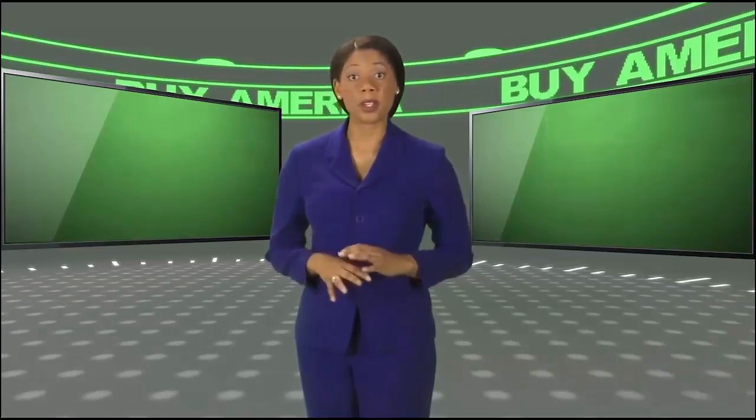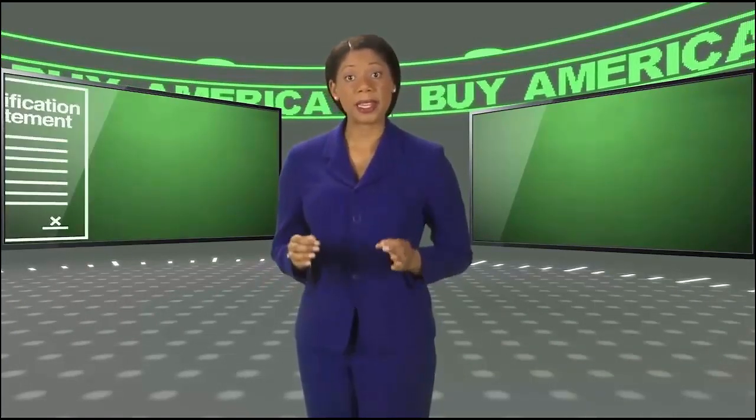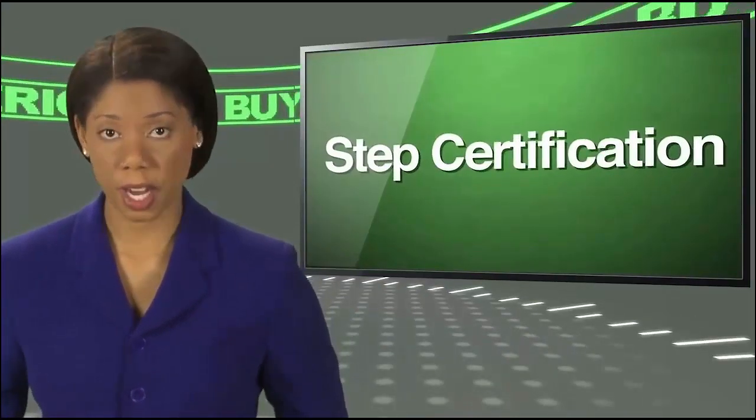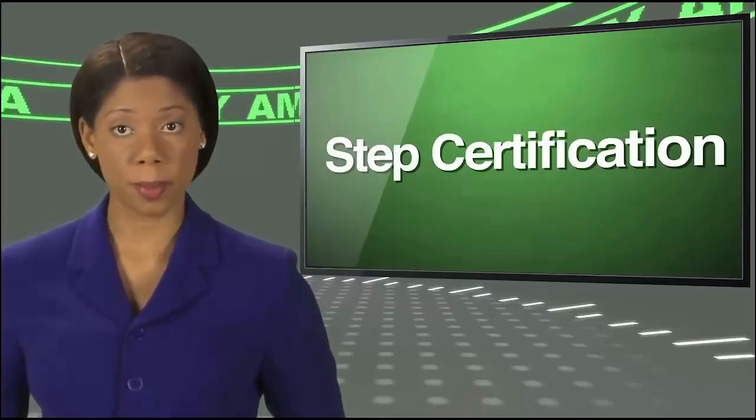Although there is no standard format, the intent of requiring a Buy America certification statement is to make the contractor liable for meeting contract requirements for steel or iron materials installed. As such, having traceable records for the products installed is a critical component of any Buy America certification. The FHWA endorses a concept called STEP certification to meet the Buy America requirements.